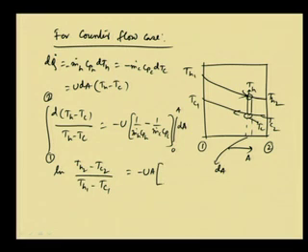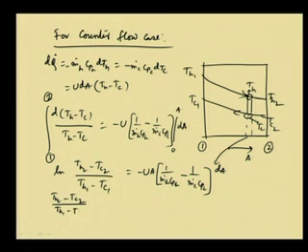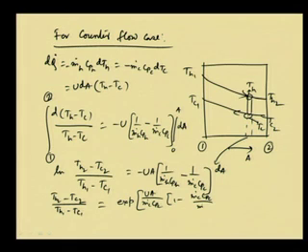Then we will have 1 by m dot h Cph minus 1 by m dot c Cpc, this. So then we can write that Th2 minus Tc2 by Th1 minus Tc1 equals exponential, and if we just take this side and the negative side, so if we multiply by this negative sign over here, then we will get UA by m dot c Cpc, and then we will write 1 minus m dot c Cpc by m dot h Cph.